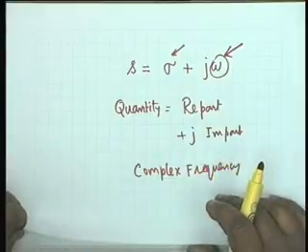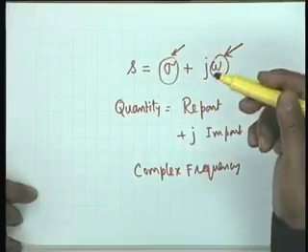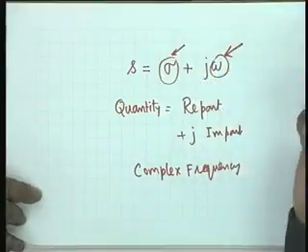and this description of the variable in the frequency domain is an extremely useful description, and you will see that most of circuit theory works in terms of the variable s only. The real part of s, sigma, is a characterization of whether the signal is decaying or growing.